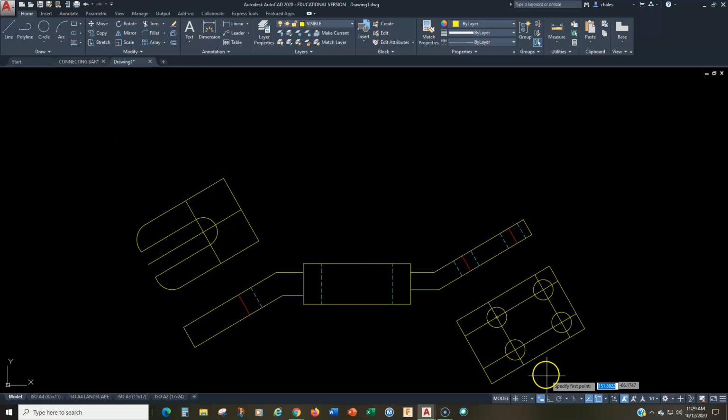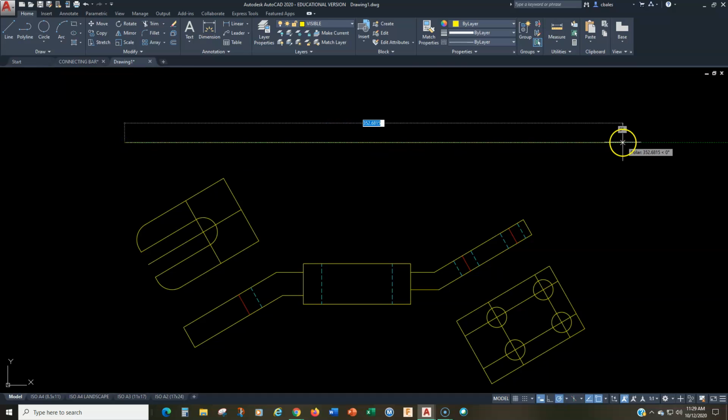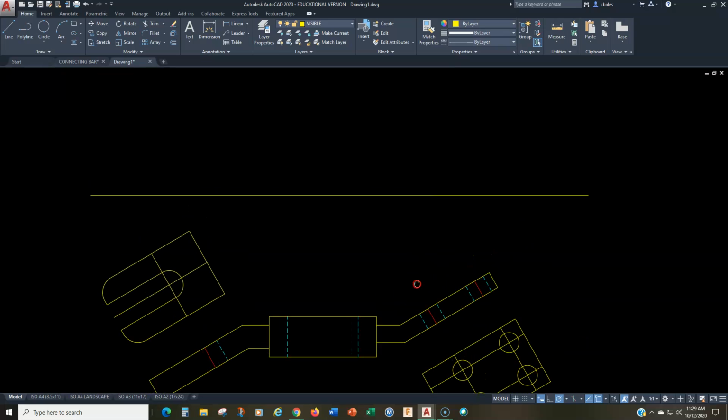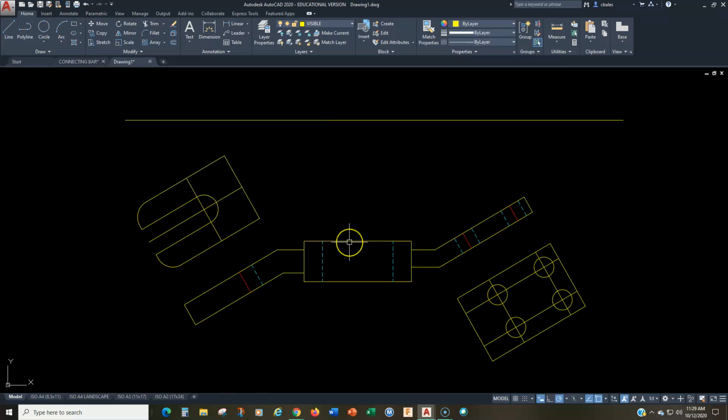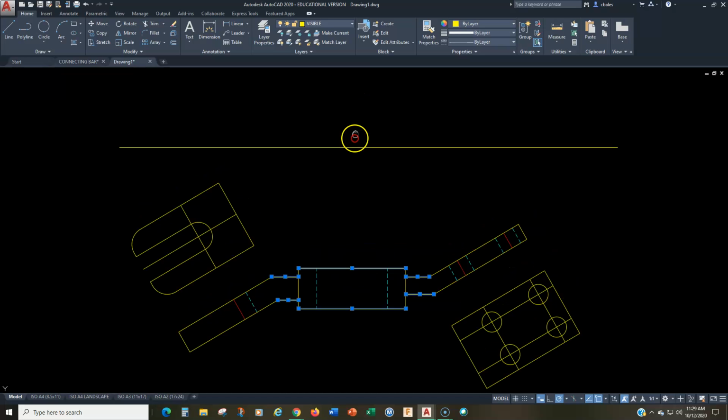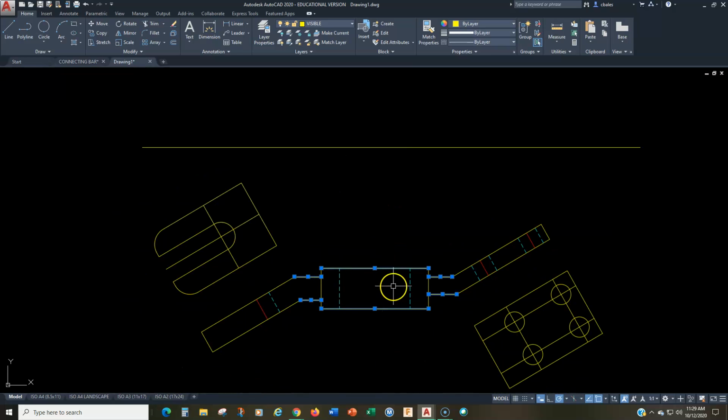When we talk about a plane of projection, we're talking about that imaginary line that runs halfway between the views. So the plane of projection between the front view here and the top view here is this imaginary plane right there. And you can see right away that this surface, this surface, this surface, this surface, this surface, and this surface are all parallel to that, which means that when we project these features through to the top view, they are not going to be foreshortened.